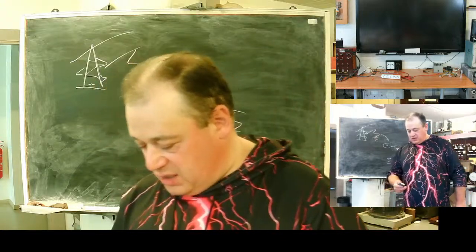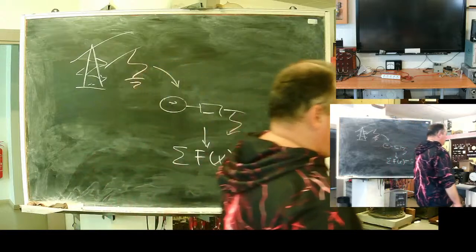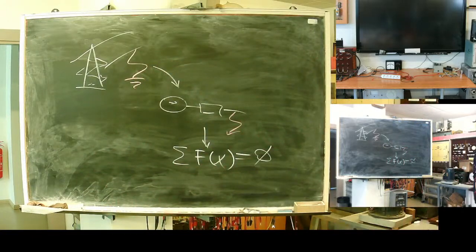So we need to set the precision level, how precise our model will be, what can be omitted and what is necessary. Fault currents do not require high precision. Your benchmark is some 10%. When we speak of fault location, it's another level of precision.